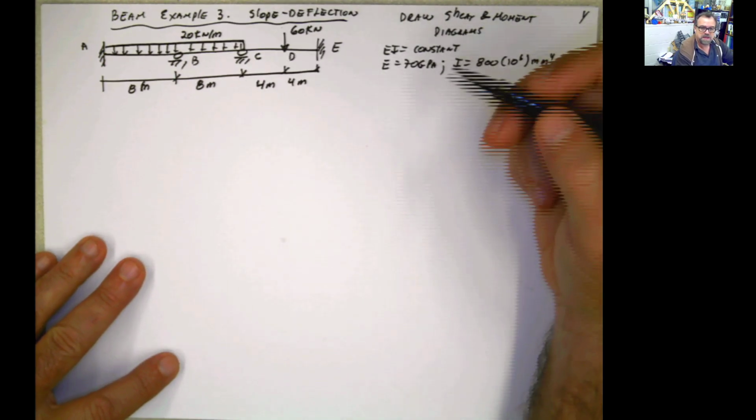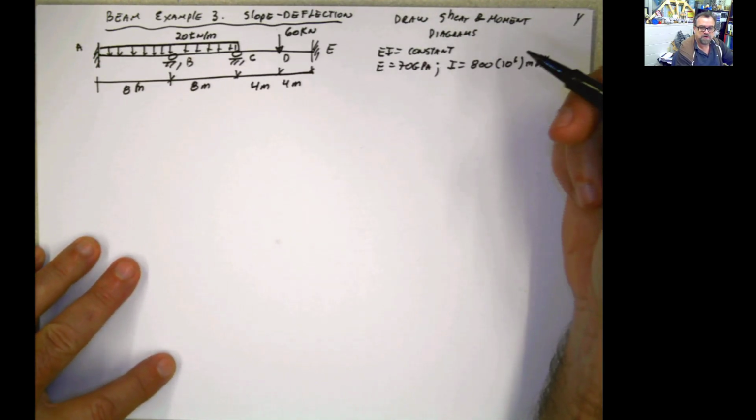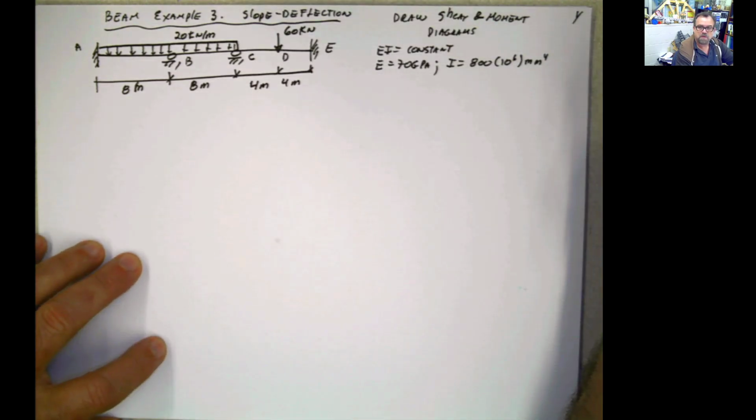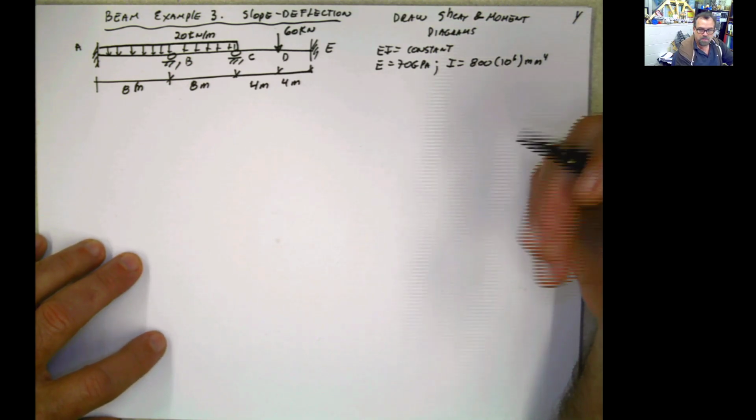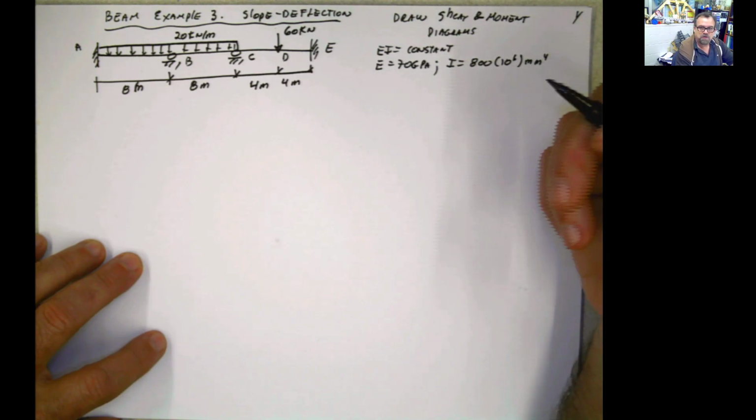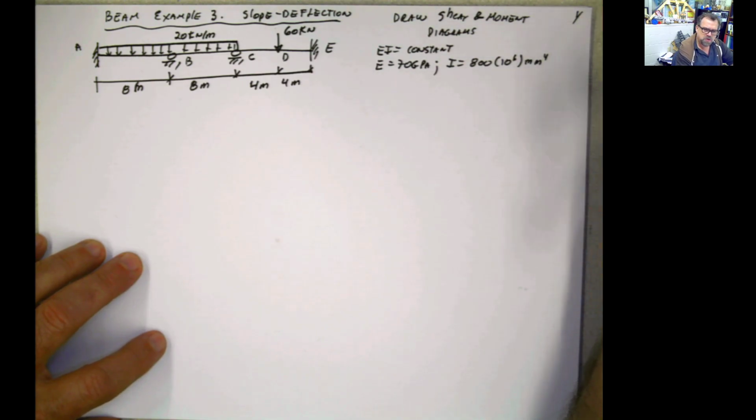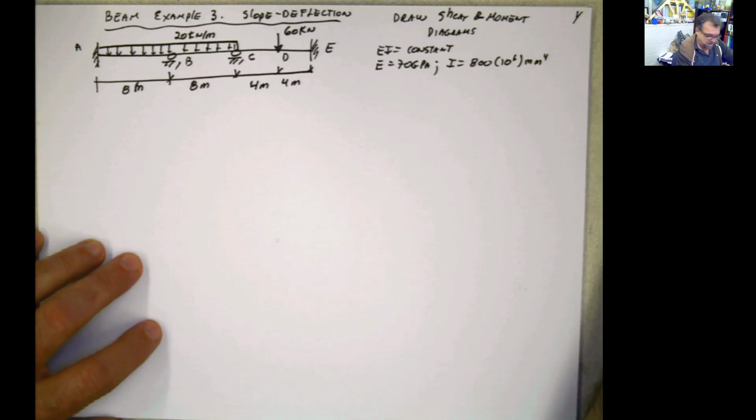Imagine doing this using force method, virtual work, deflections, compatibility equations. Imagine that we have to select 5 redundants, eliminate those 5 redundants, apply the correction, create a huge system of equations, and then solve it. Now let's see what happens if we use slope deflection.